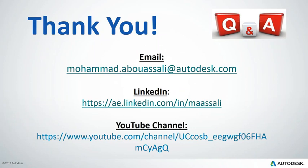Okay, so there is a question about the accuracy of designs in InfraWorks. InfraWorks is, yes, for conceptual design, but it's very accurate because it's actually geo-referenced and to scale. So everything you design within InfraWorks is based on a design standard and has a certain coordinate system assigned, same as we do in Civil 3D, for instance. You specify the coordinate system of the UAE or Saudi Arabia or any other country, and then you design within context, to scale and accurately. So no issues about accuracy in regards to InfraWorks.